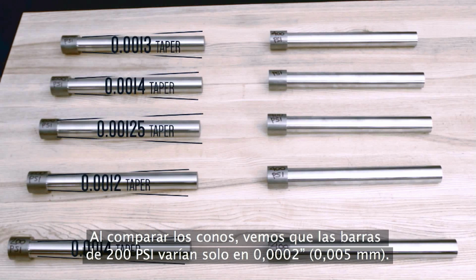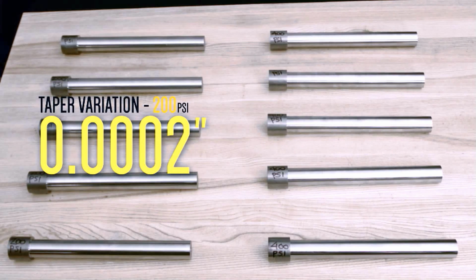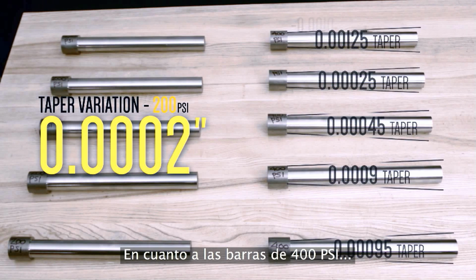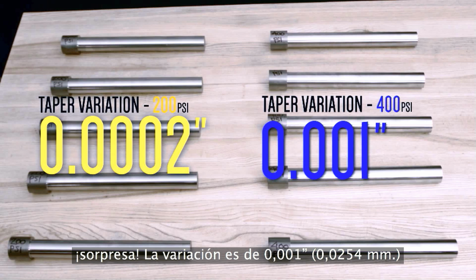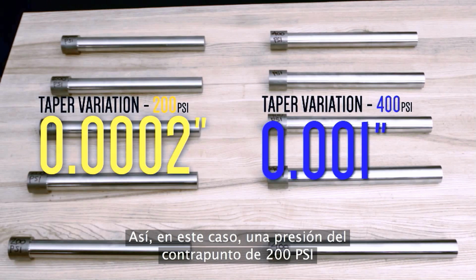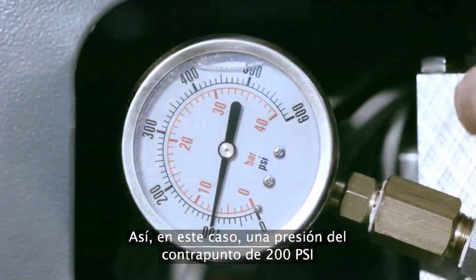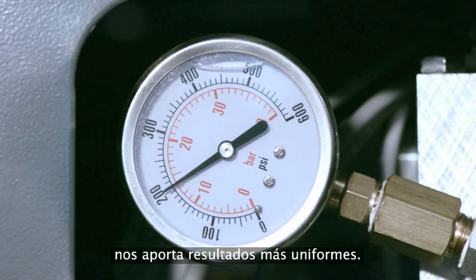Comparing the taper values, we find the 200 psi shafts vary by only 2 tenths. And finally, looking at the 400 psi shafts, surprise! The taper variation is 1 thou, 5 times greater than the 200 psi shafts. In this case, setting tailstock pressure to 200 psi gave us more consistent results.